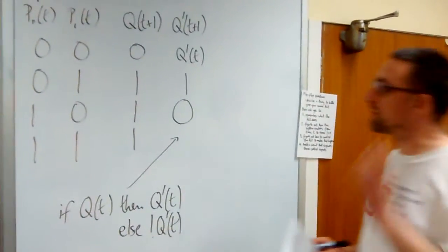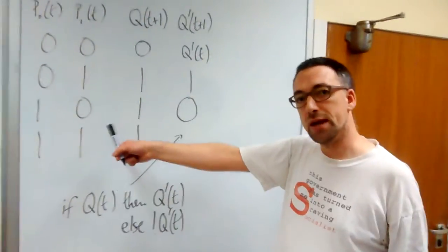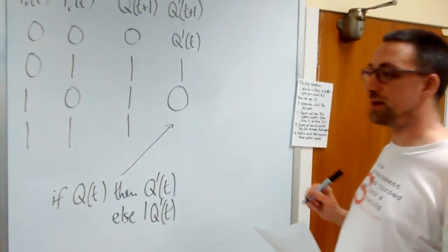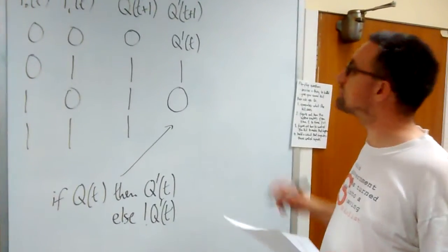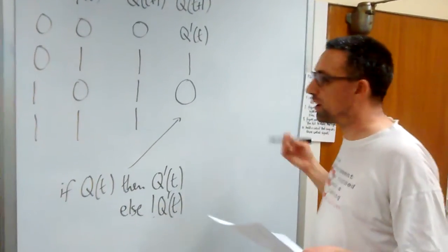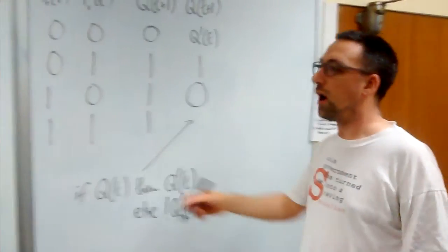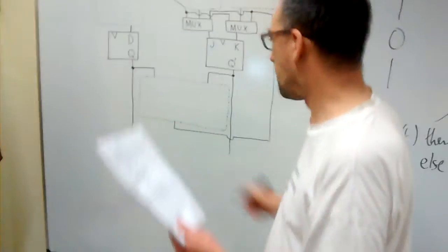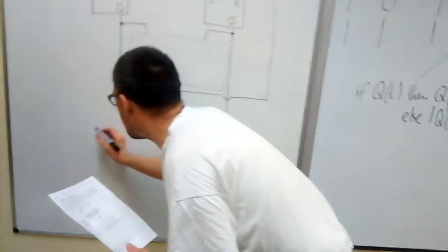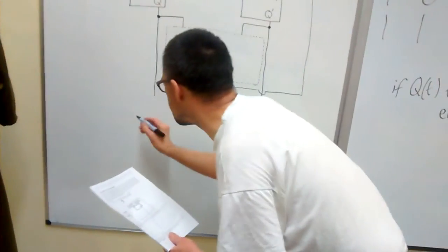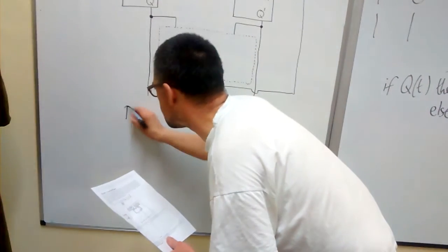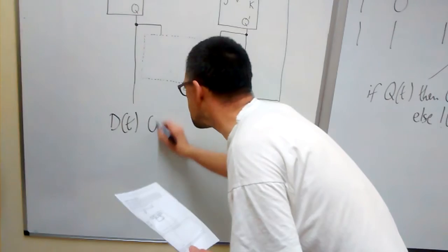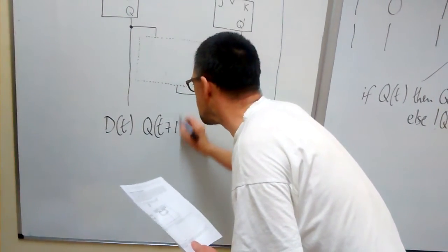Okay, so we've figured out how to tabulate the behaviour we want from the given inputs. Now we need to find the control signals for that. And at this point, we're going to need to remember how the actual flip-flops work. So let's do the first two parts of the question. We have to write down the characteristic table for a D flip-flop. So that's to say, when we know what D of t is, we should be able to say what Q of t plus 1 will be.